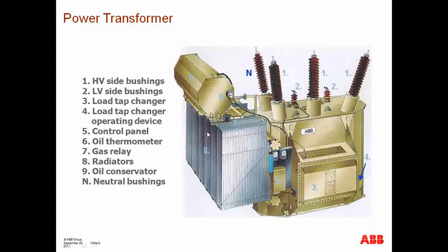You essentially have the radiator of the transformer. Usually on some models you just have a radiator, and then there are going to be fans and cooling mechanisms that maintain the temperature inside of the transformer within a particular range. Okay, and then number 9 here, this is something very important to recognize, and this is just an oil reservoir, where excess oil is stored. It's important to consider that most power transformers in operation are oil insulated.